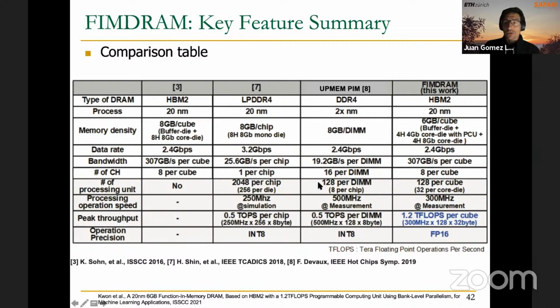While in one place we have in-order processors that execute multiple threads and issue instructions from these threads one after the other, on the other side, we have a shorter pipeline of only 5 stages, but each of the execution units is a SIMD unit that can execute up to 16 threads or 16 operations at the same time.